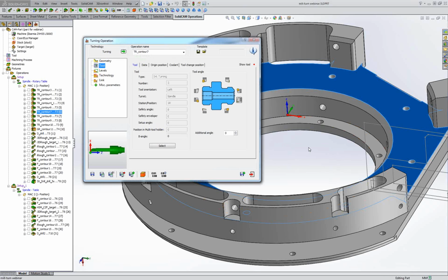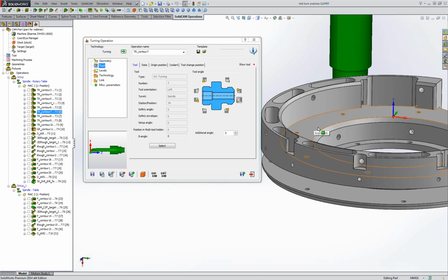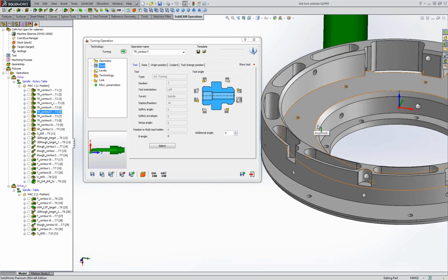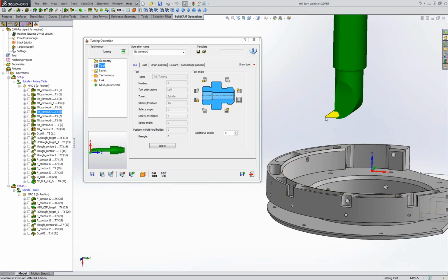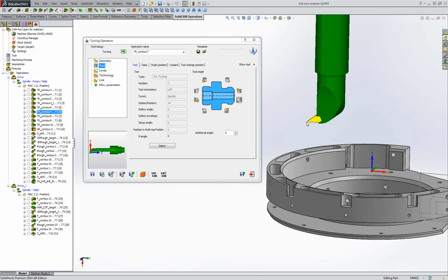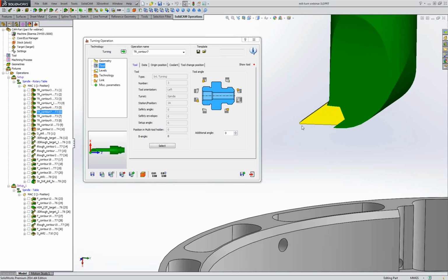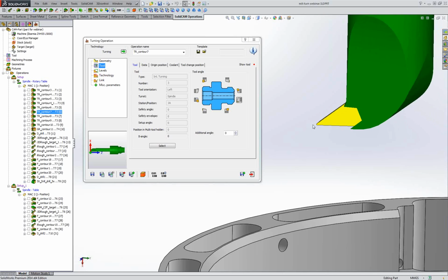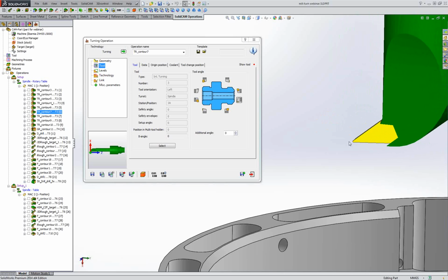The tool. I'm going to work here, and when I want to make this floor, remove the material on this floor and chamfer, I don't want the tool to come down and go right, because if I have 0.2, 0.3, maybe 0.4 millimeter rest material on this floor, but here the insert has only 3 degrees release, so even 0.2 or 0.3 millimeter, that will be a few millimeters, 4 or 5 millimeters on the edge. So a lot of pressure on the edge, down edge of this tool. So I want to work from inside outside.